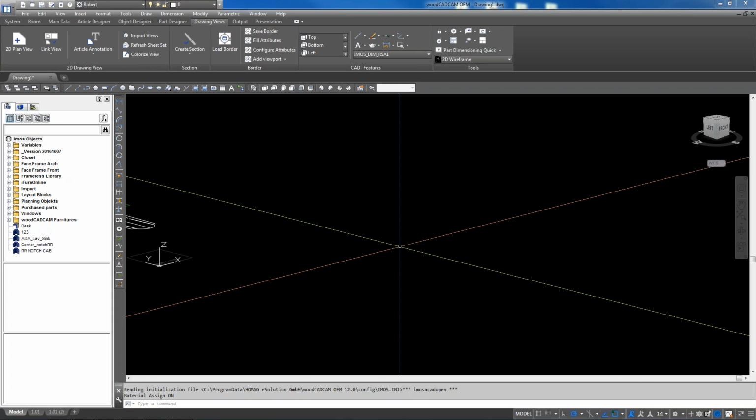For example, we have a shelf in a cabinet, 3/4 shelf, and we want to miter fold it to drop the lip down by 2 inches. Or even more difficult, make it miter folded 2 times. Let's say the shelf is 15 inches, then drop it down 2 inches and return it again the same depth. So make it miter folded 2 inches thick shelf of 3/4 material.